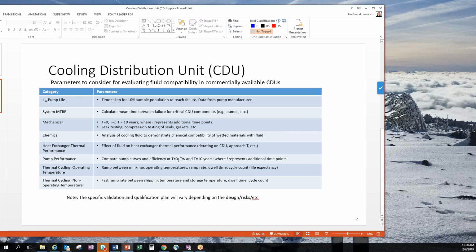I mean, if the goal is to just have CDU vendors provide this information, you can go to their website and they probably have some of this information. I agree with others, Steve and others, about the pump life and the mean time between failure and all that kind of stuff. It's so dependent on how it is operated, what's the control methodology within the CDU, what are the fluids, how do you maintain the system? I'll give you my view: there's no way we could do this across a range of different fluids and think we will come to one answer that works across the board.